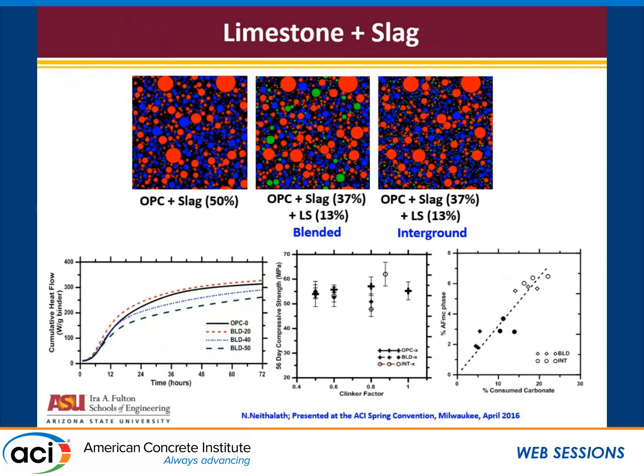So that is the first part of the chemistry with aluminates. Now, going on to slag, you will pretty much see the same story, but slag is even better because slag is cementitious too, not just pozzolanic.